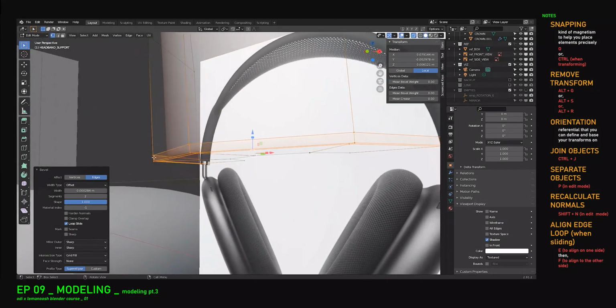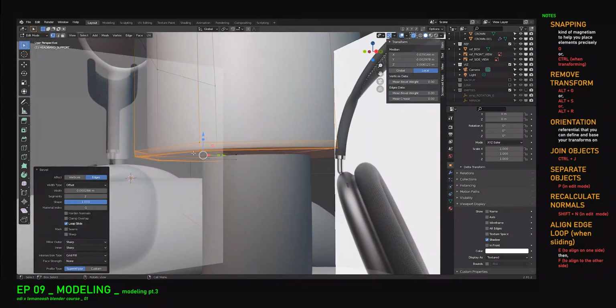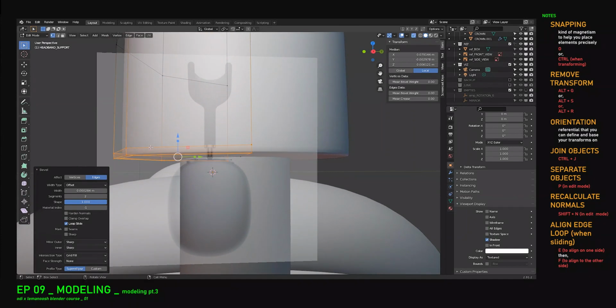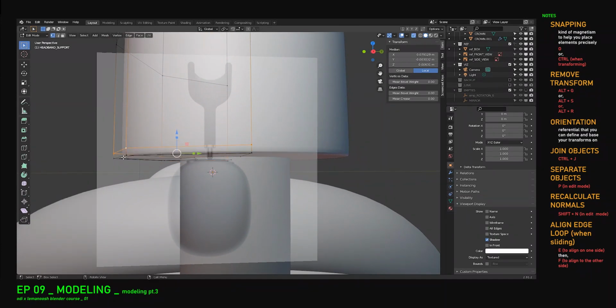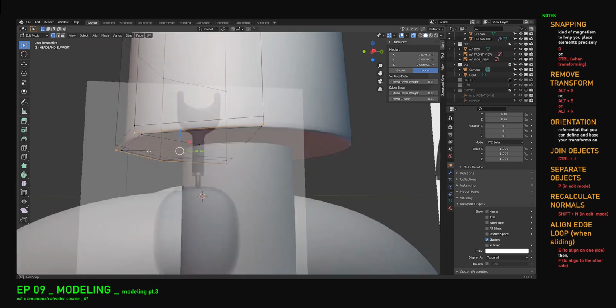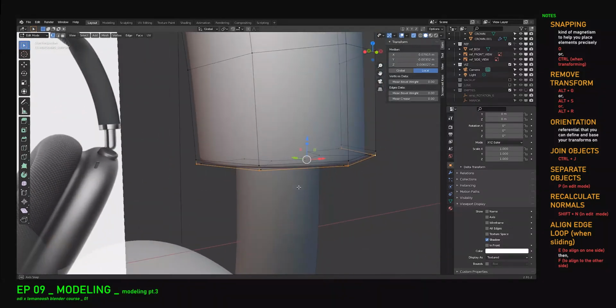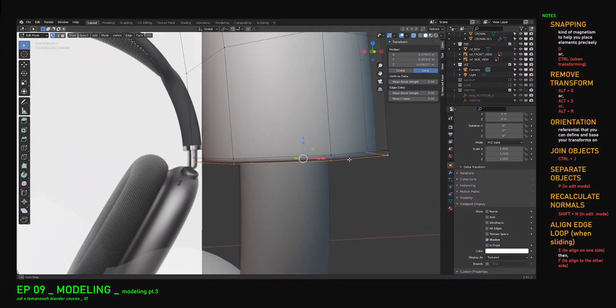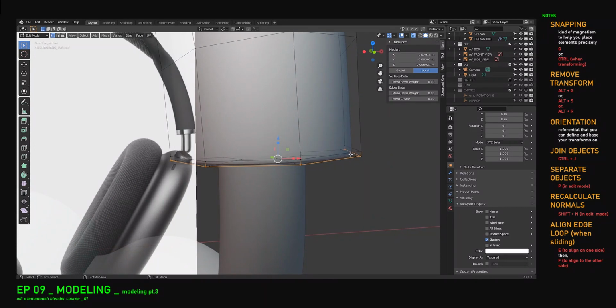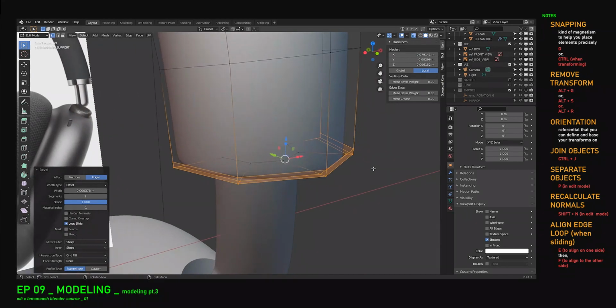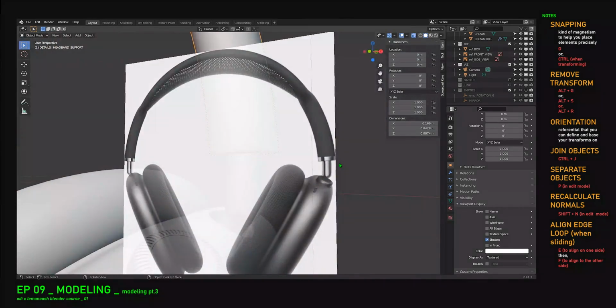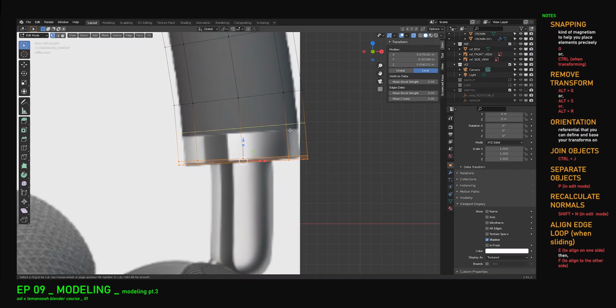Because then basically what it does is that it does a 90-degree angle there, which means that if you think later on that it was not the right thing to do, you can just select these, delete them, and basically this edge will be the exact same one as the one you did a bevel on. And this is super useful because then doing a bevel becomes kind of a non-destructive action because the edge doesn't move. I can show you again. If we do this with this setting, you can see that the edge doesn't remove. So perfect.